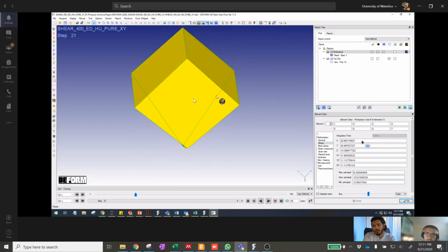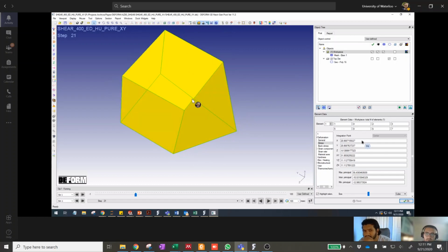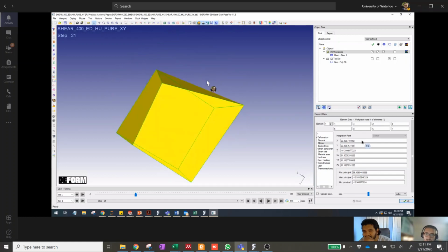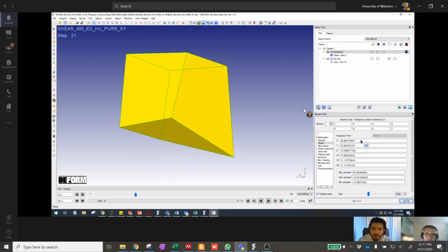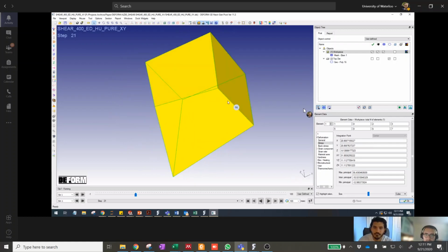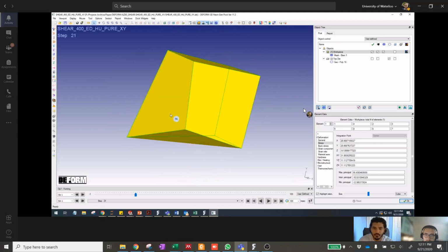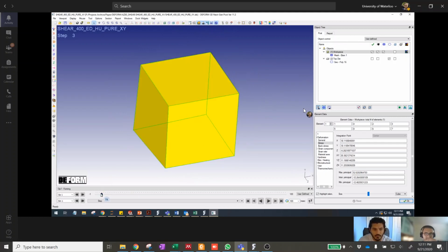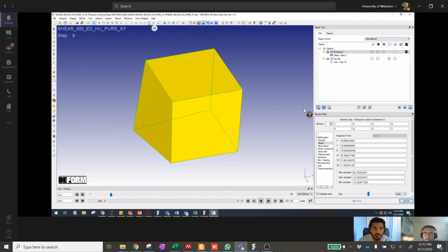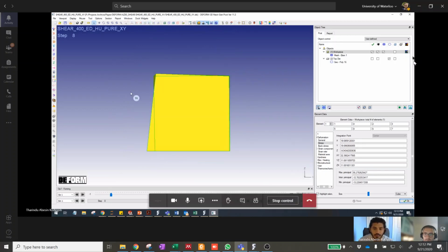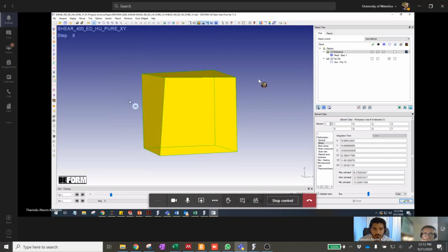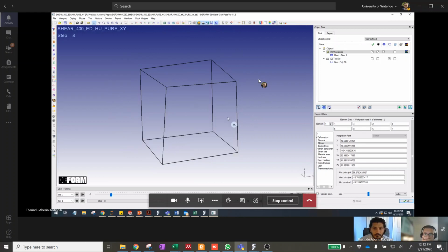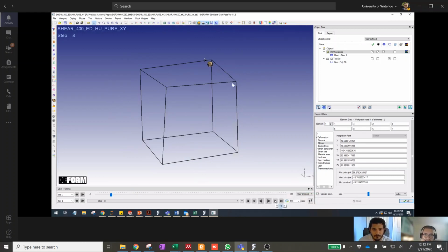So what I don't get is why is it only twisting on this one corner? Orient it the way that it was when you were setting up the boundary conditions. That's the way it looked initially. It's getting pulled. Maybe we should look at it from the top. Oh no, that's not gonna work. This is better. So then these are the two nodes that are having displacement applied here.